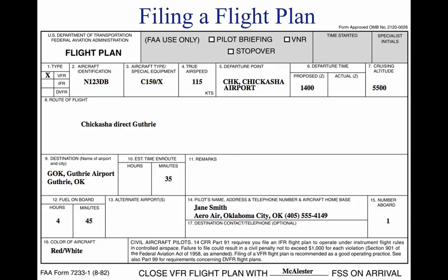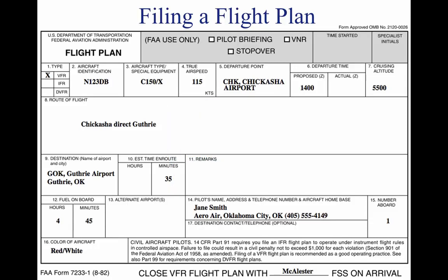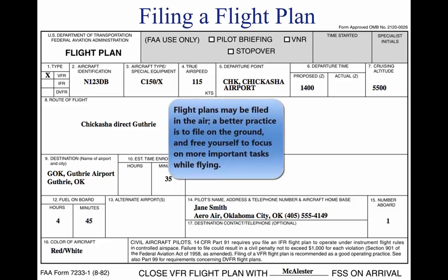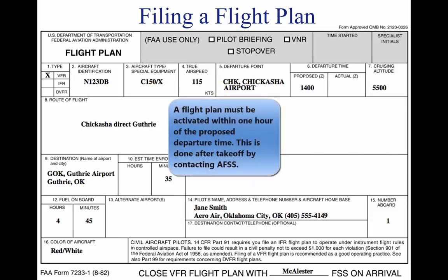Filing a VFR flight plan. Filing a flight plan is not required by regulations. However, it is a good operating practice, since the information contained in the flight plan can be used in search and rescue in the event of an emergency. Flight plans can be filed in the air by radio, but it is best to file a flight plan by phone just before departing. After takeoff, contact the AFSS by radio and give them the takeoff time so the flight